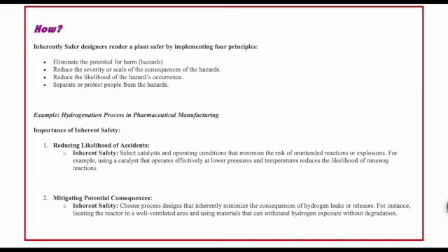So, how do you reduce the likelihood of an accident in your company? The good practice is to design the hydrogenation reactor in such a way that it has proper pressure relief systems and controls to prevent over pressurization. This is the good practice that most companies follow, and you will also think about this in the first go. Okay, let's design that kind of reactor.